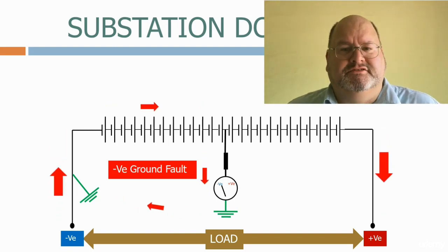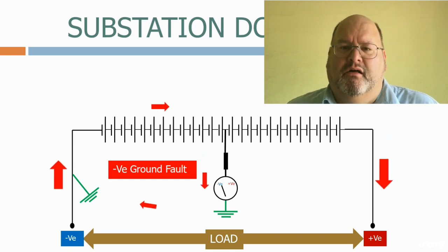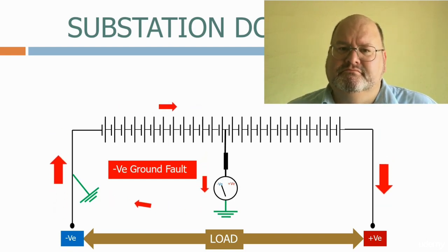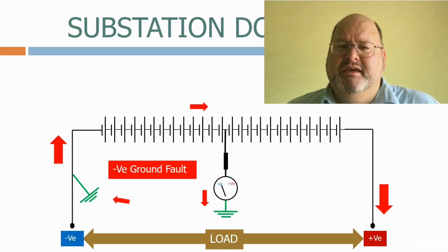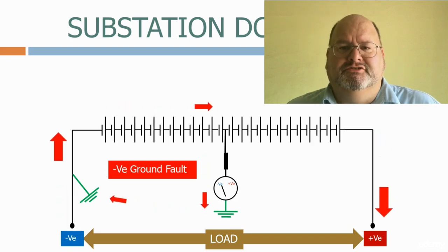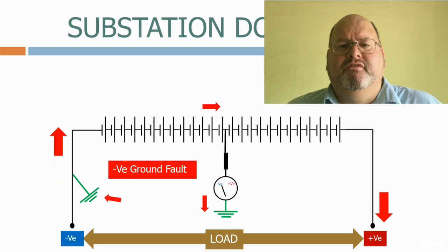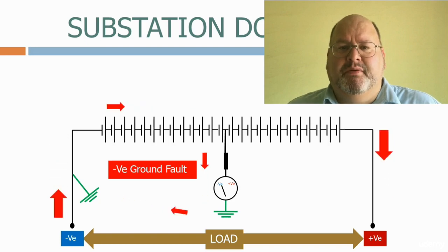Having this type of earth fault detector is a good way of monitoring the health of the DC system. For major battery earth faults, the fault current generated should be sufficient to operate the MCBs immediately. The earth fault monitor will also trip the circuit breaker. For minor earth faults, an alarm will be generated and the battery left connected. The engineer can then trace and repair the fault at a later date.